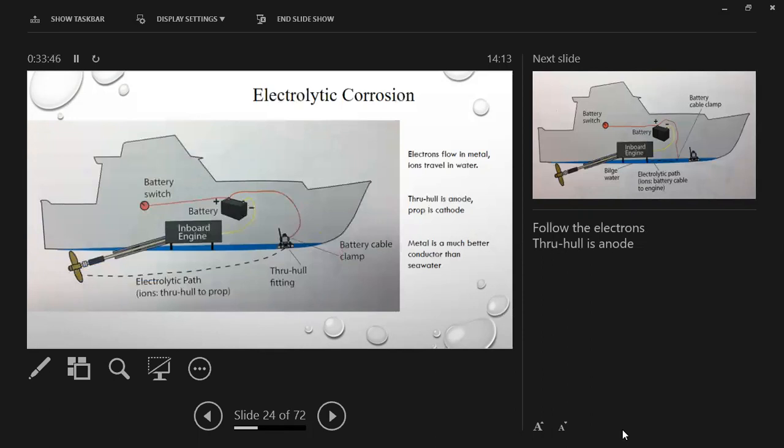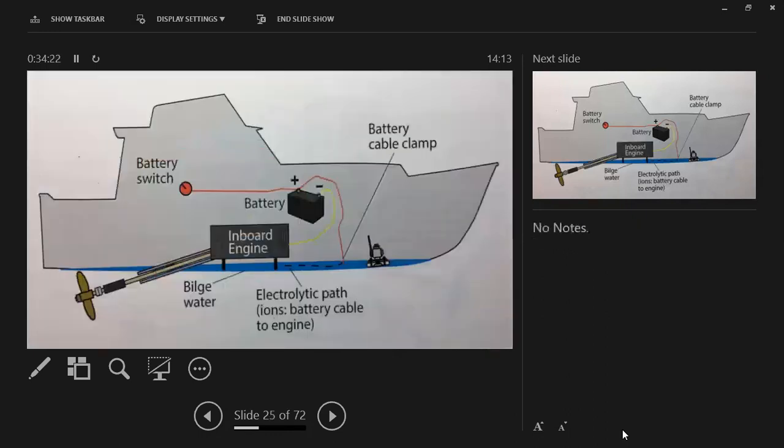Come to find out, this boat was sitting by two bubblers that were in the water, and all the cords were in the water. Just plain galvanic corrosion can, if it's overprotected, you have too much zinc on the boat for the amount of protected metal, you can get some haloing. Usually it's not too dangerous, but it does deteriorate. It is very dangerous in a wood boat or an aluminum boat. Overprotection in those two can be very dangerous.